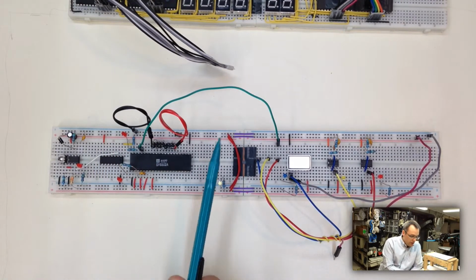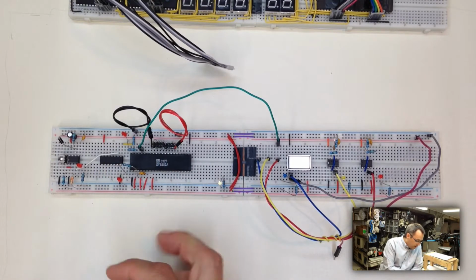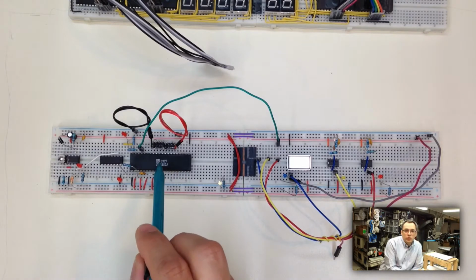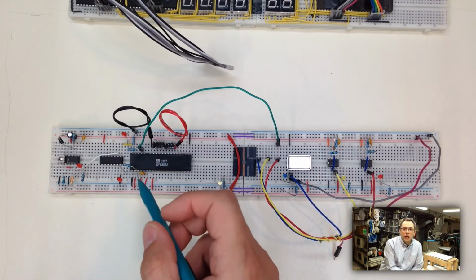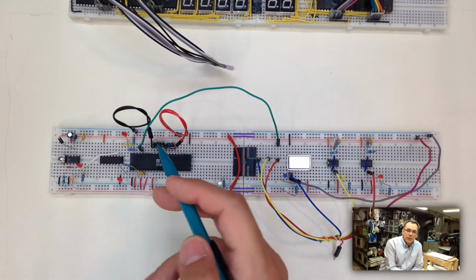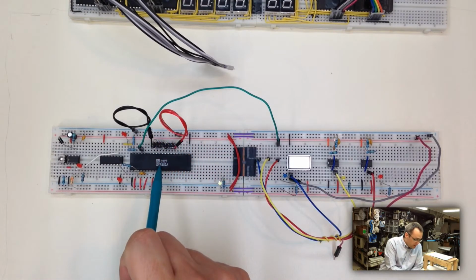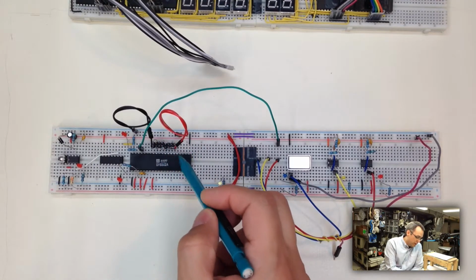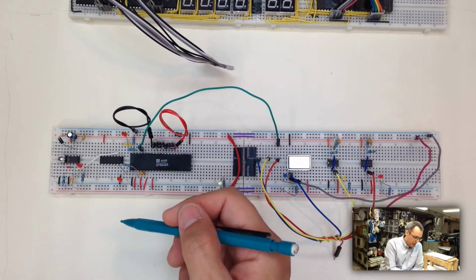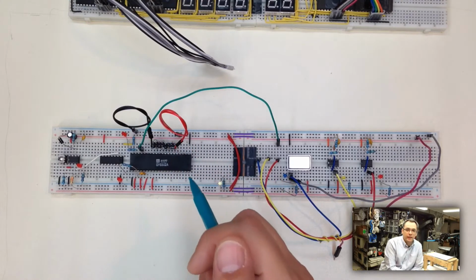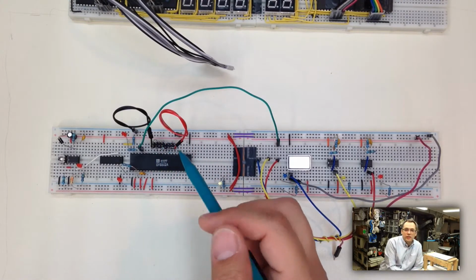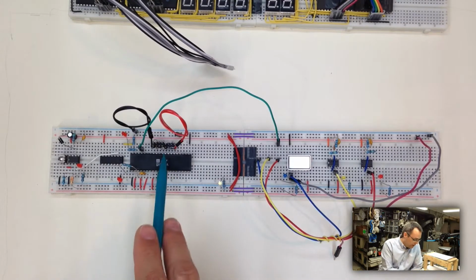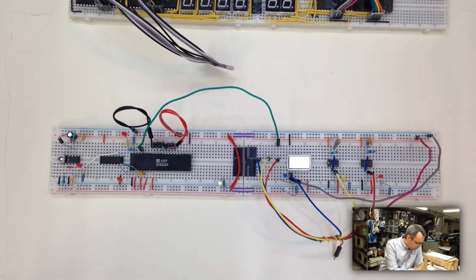Now let's go over here to this section. This is the actual processor, the Synertek 6502A. This specific chip was pulled out of an Apple IIe unenhanced, and I'm using it because I happen to have it. I'm eventually going to be upgrading that to an actual 65C02 because it has a little bit better compatibility, better reliability, better operational characteristics, and if I decide that I want to see if I can speed the machine up to multiple megahertz, those processors can do better. This guy, he's stuck at 1 meg.